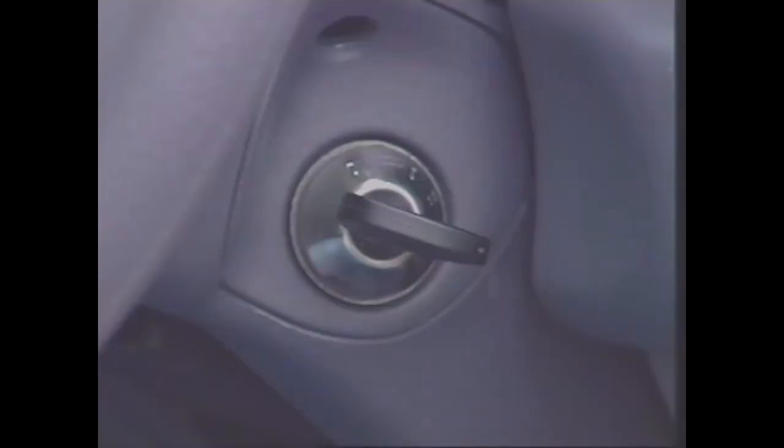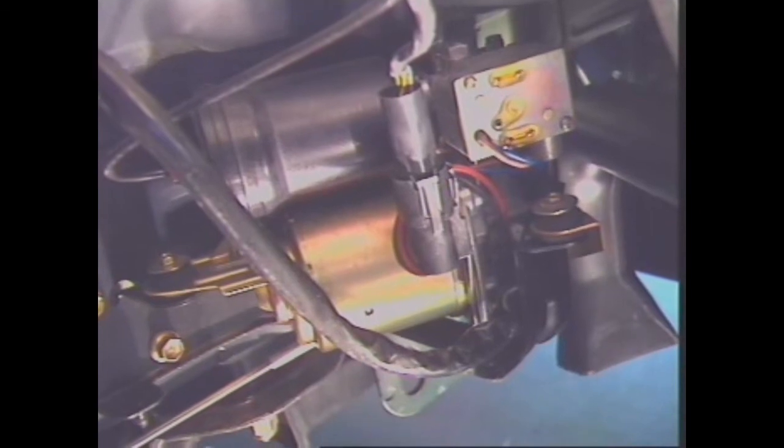The ECU is mounted to the cross member over the rear axle, and a movable link connects it to a rear suspension member. As the vehicle is loaded, the normal suspension springs are compressed, which lowers the height of the vehicle. When the ignition is switched on, the ECU senses the lowered ride height and switches on the air compressor. Air is directed to the shock absorbers, causing the airbag around them to expand and raise the suspension to the normal trim height.